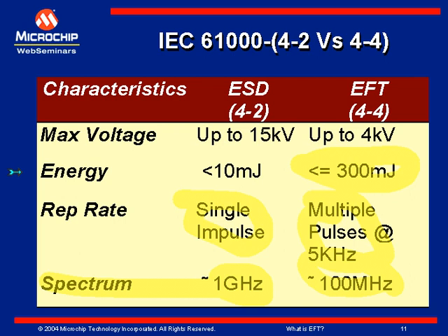If you look at the spectrum itself, you can see that this tends to be much higher than the typical frequency your embedded system runs at. And therefore, many times you need to think like an RF designer to fix these issues rather than having the mindset of an embedded designer. So this was a basic comparison between ESD and EFT.